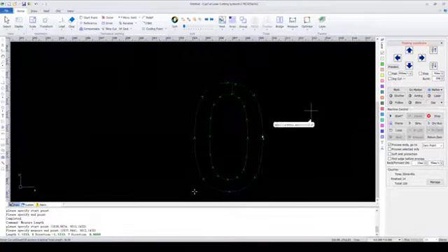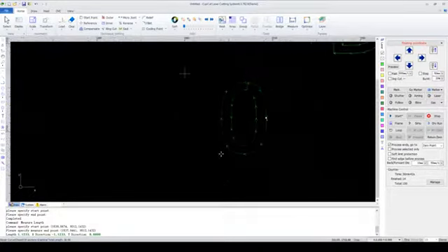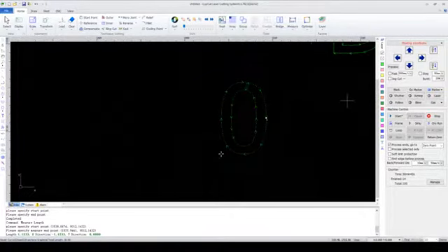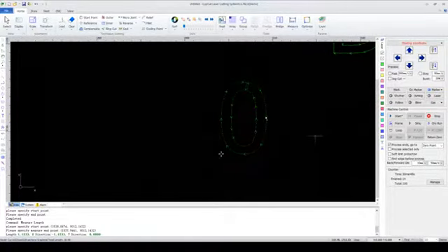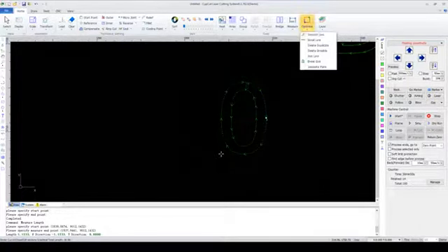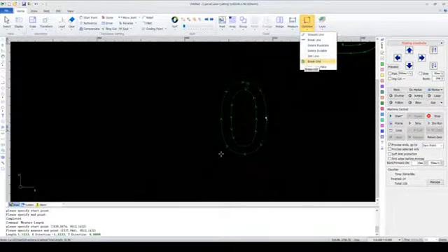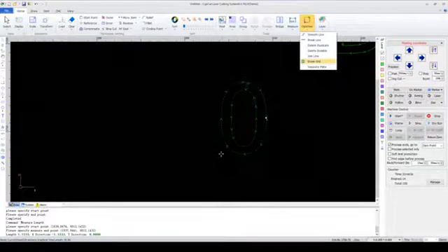Now let's come to the last feature. If we don't want parts to get automatically optimized when input, click Manually Optimize. In the drop-down menu we have this break grid, which is used to cut up the inner waste so as to avoid it going up and getting in the way of the cutting head.